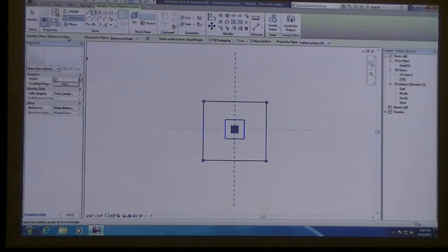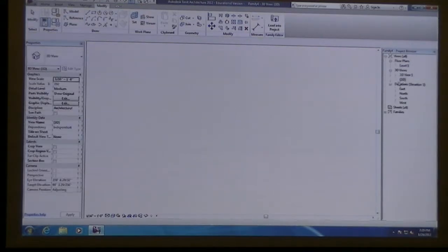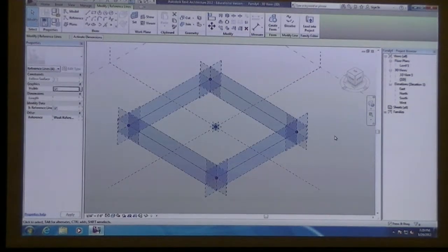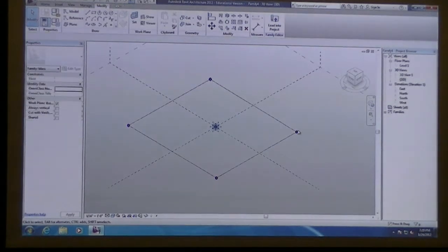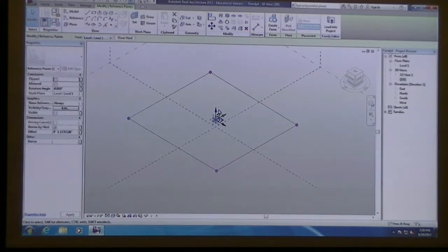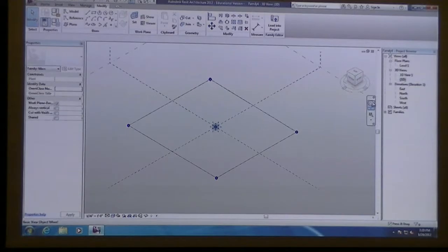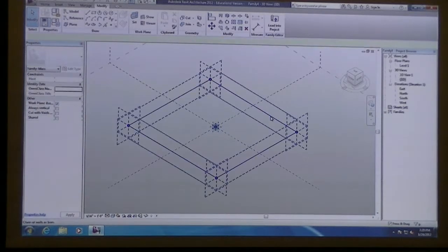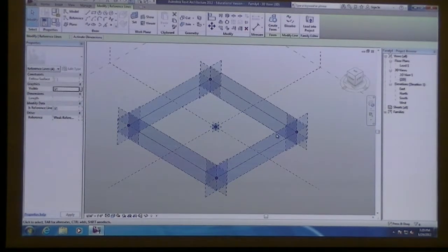Then I drew a rectangle, you should get something. So you know it's wrong. Yeah, so you should, because I picked the plane and then I drew the rectangle, and we were on that horizontal plane of the point, you should now have a relationship between that point and also this plane that you created the rectangle. Did everyone get that to work out? It's kind of tricky a little bit.